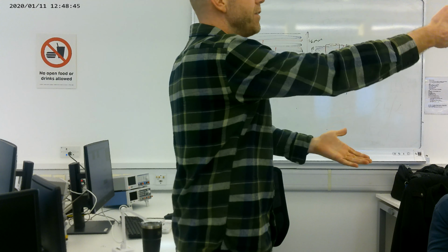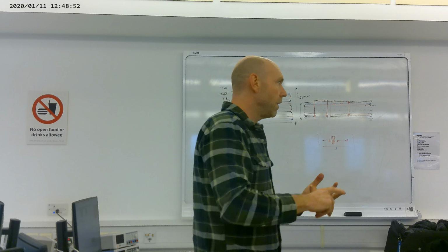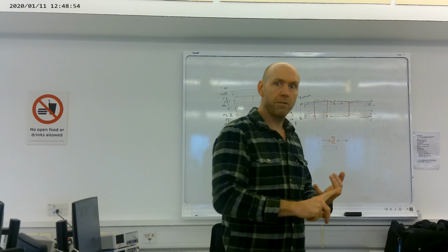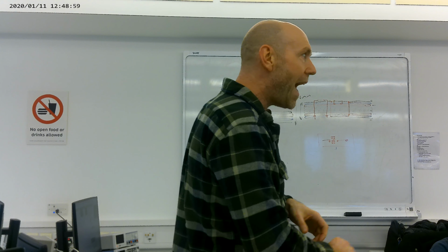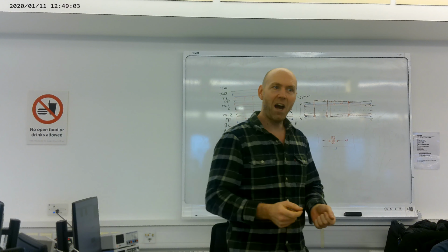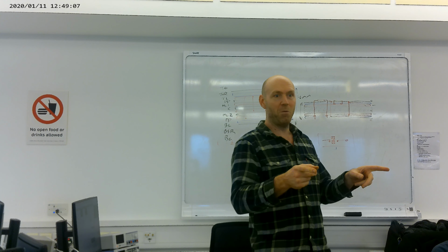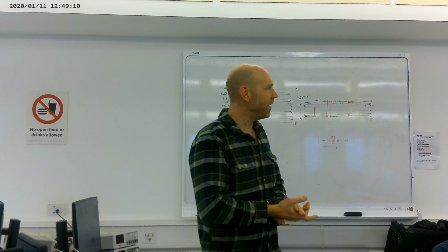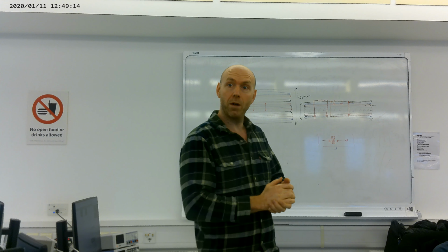But ideally, you want to make that bill of materials so that you could give it to someone in the office and they would be able to order your parts, which means you'll need a quantity, a description, a supplier, whether it's Farnell, Mouser, or RS, or whatever, and the price and the minimum order quantity. That's really important because it brings it home as to whether you think, oh, that's perfect and it's really cheap because it's 0.001p, but you find out you have to buy 500,000 of them to get that price. And that's how electronics works, especially with resistors.